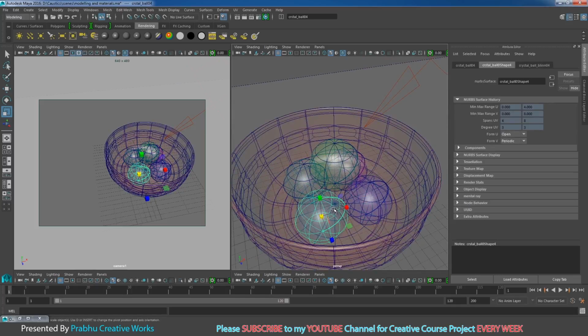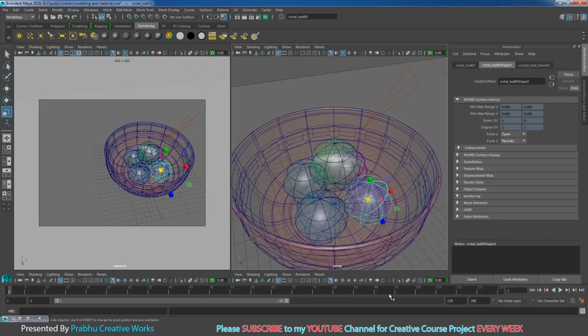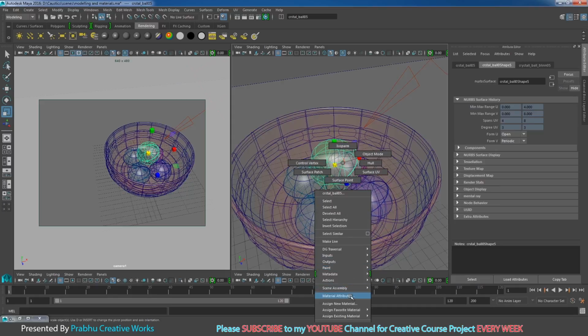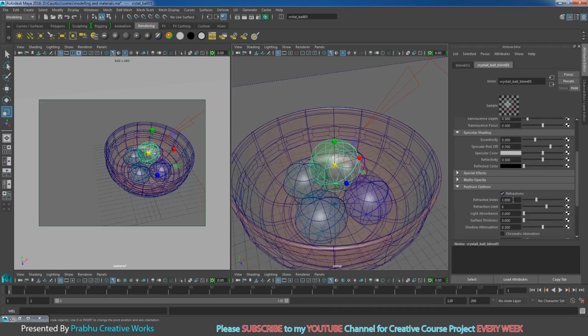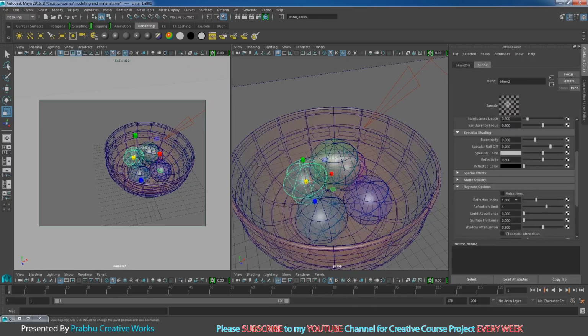So I will select my crystal ball, right click and choose material attributes. Here go to the ray trace option and turn on refraction.